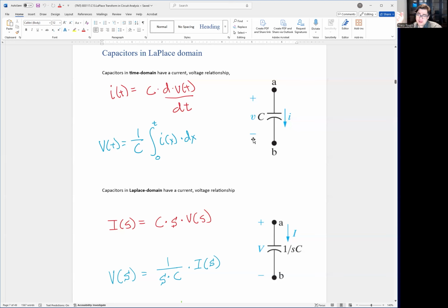So the more current I push in, the more electrons I put into the capacitor, the bigger the charge gets and the higher that voltage gets. And this can keep on building forever until I stop putting in current. We can represent that by taking the integral of the current. So the longer the current stays on, the higher the voltage.